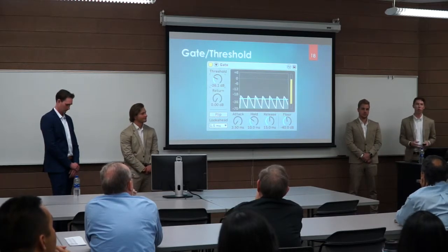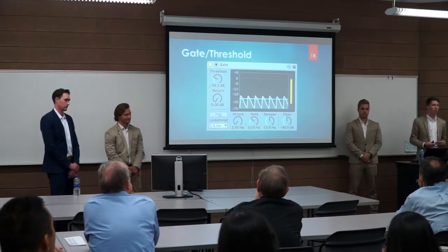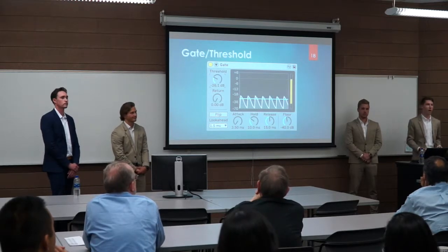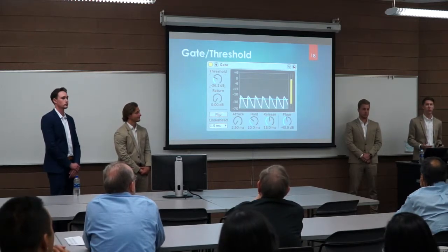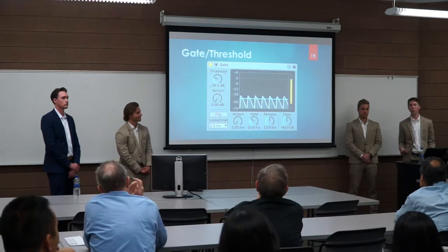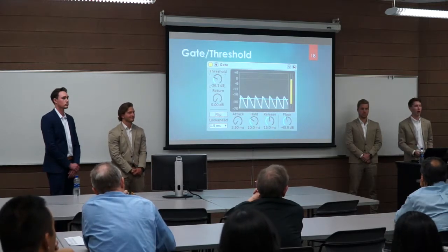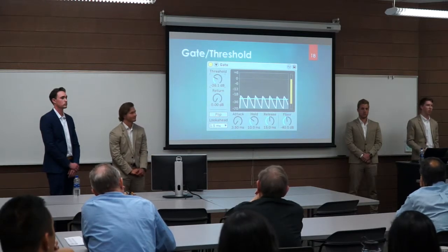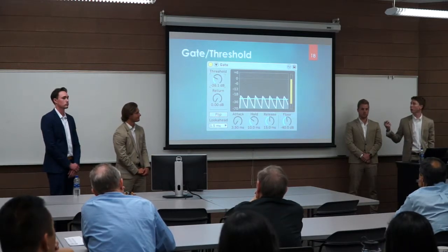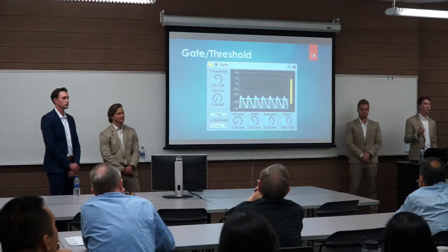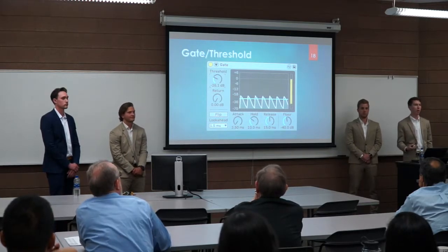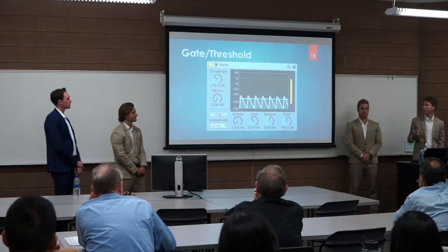So brief run through, we take in all of our audio samples that the drummer plays into the box, and from there we determine the maximum level for that drum kit. After that, we set our threshold to be 6 dB lower than whatever that maximum level is to make sure that it's a dynamic gate that can work in many different scenarios. Whenever the threshold is reached above, and if the previous has been below, we know that we've achieved a kick hit, and we can now finally go into our beat detection.